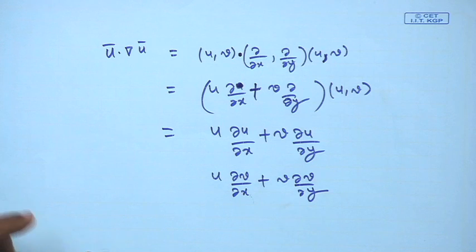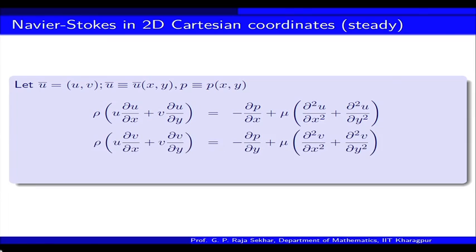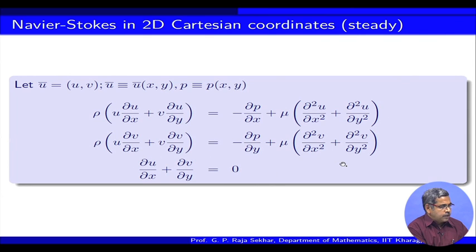Okay. So, once we do this, that is what we have written, the first component, and corresponding to the pressure gradient you get this, and this is a simple Laplacian. So, very straightforward. Okay. And this is the corresponding equation of continuity. So, this is the simplest. If you want to decompose in cylindrical or 2D plane polar coordinates or spherical, you have to know the corresponding gradient and Laplacian in terms of those coordinate systems.